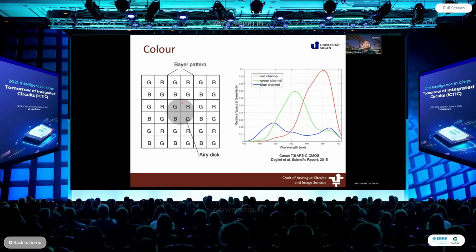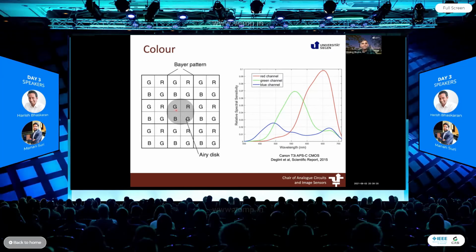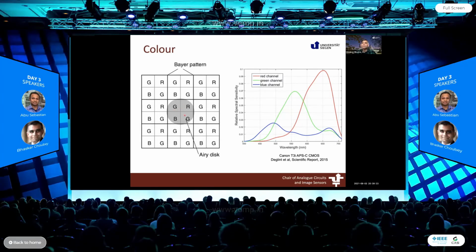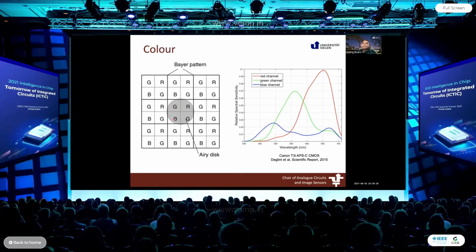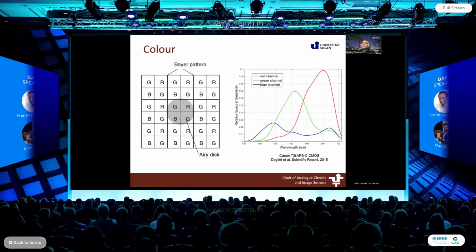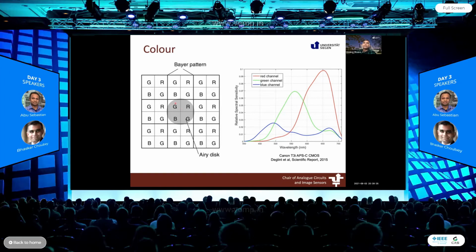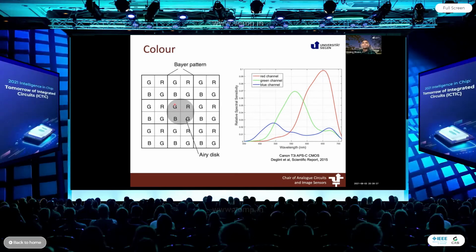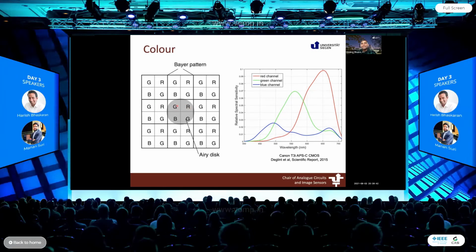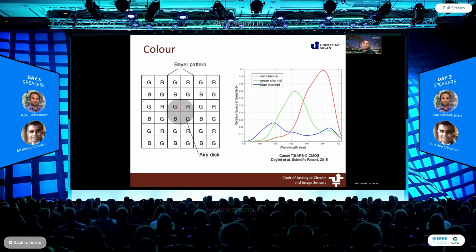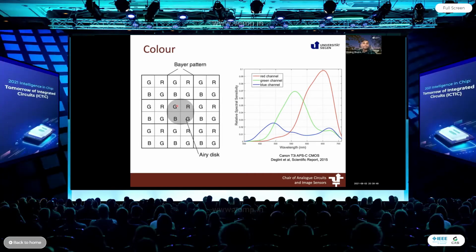So we end up putting a color Bayer pattern on top, or any sort of filter pattern. There is a typical pattern which has got double the number of green compared to red and blue. And so essentially, we have a quarter the number of red pixels and a quarter the number of blue pixels. Then we try to figure out at the green pixel value what might be red. One simple thing is to take the average of neighboring red. So what I'm saying is that just the acquisition of signal part is challenging, and then we have the color filter to make our life interesting further.